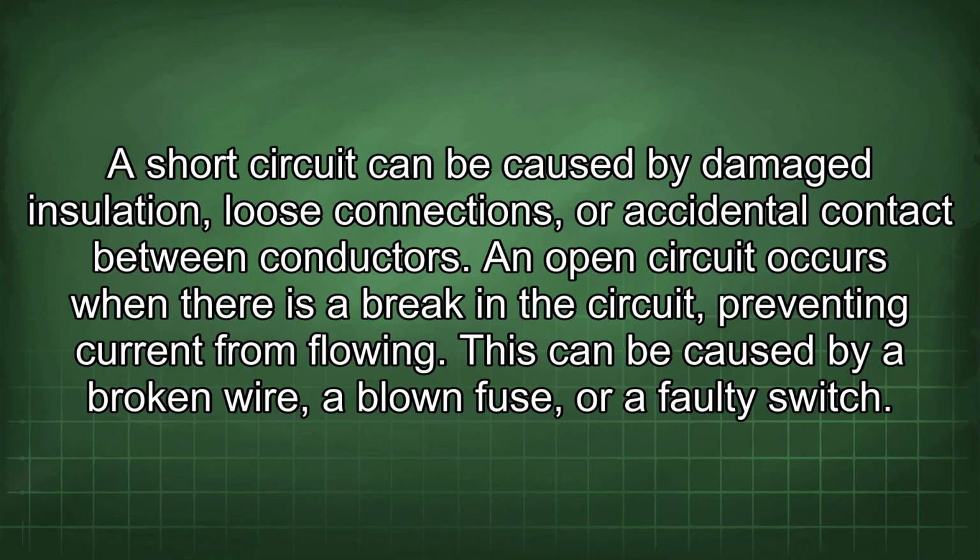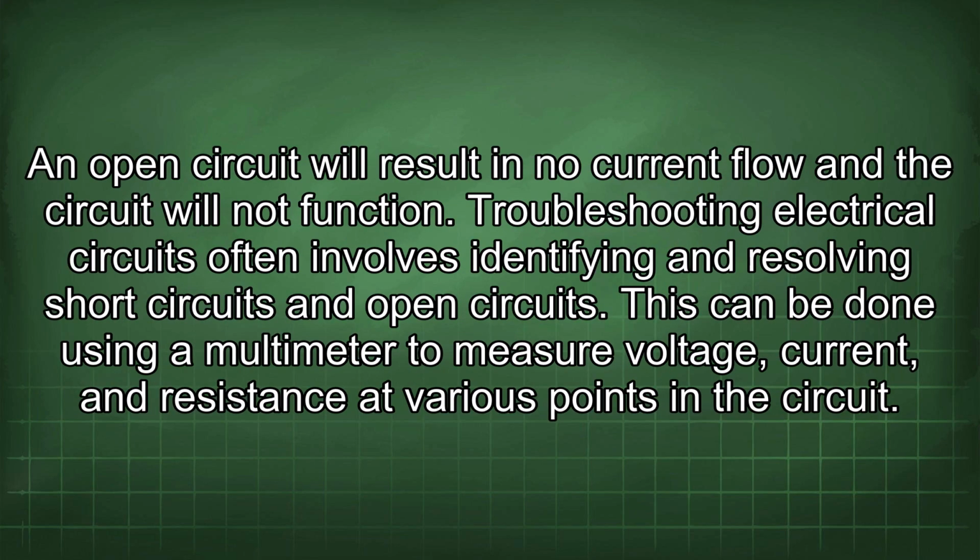An open circuit occurs when there is a break in the circuit, preventing current from flowing. This can be caused by a broken wire, a blown fuse, or a faulty switch. An open circuit will result in no current flow and the circuit will not function.